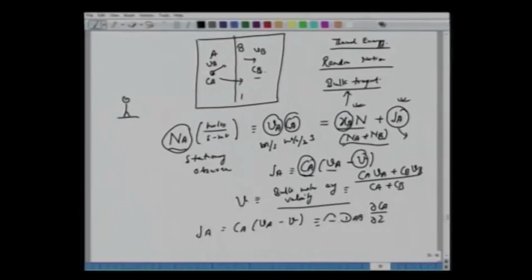Why the minus sign? It signifies that the gradient is negative. Species transport diffuses from high concentration level to low concentration level. So we have this negative gradient. But more important here is the definition, or the fundamental understanding, of this molecular diffusion from bulk transport. All right, a species gets transported. Why? Because one is concentration difference. This can exist irrespective of whether there is a pressure drop or there is no pressure drop. So there is a concentration gradient, Fick's first law.